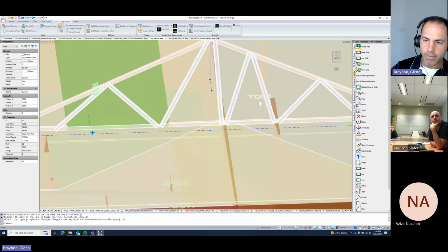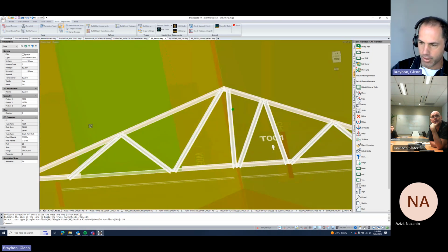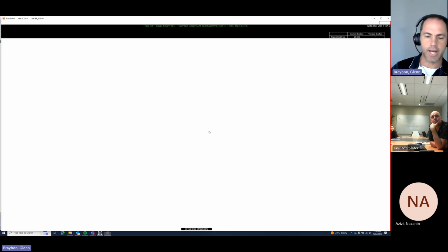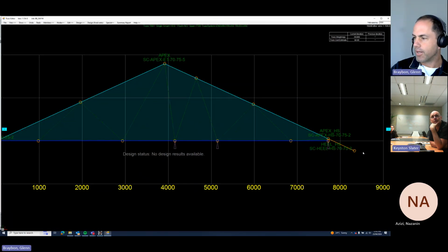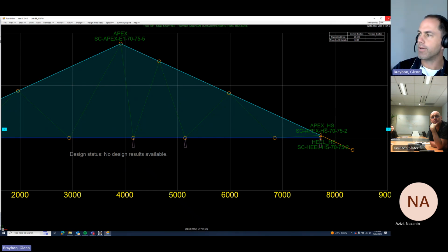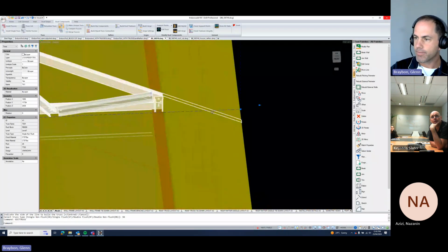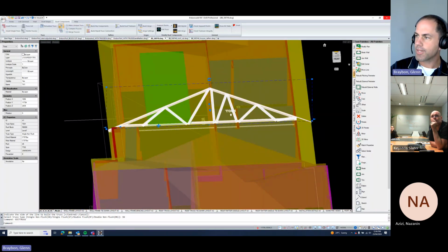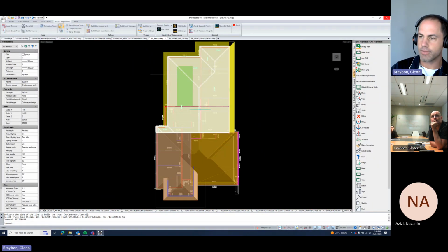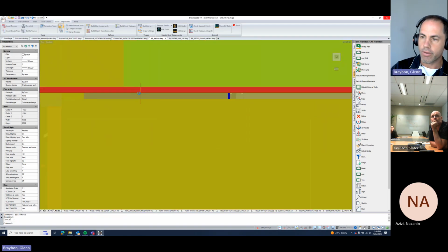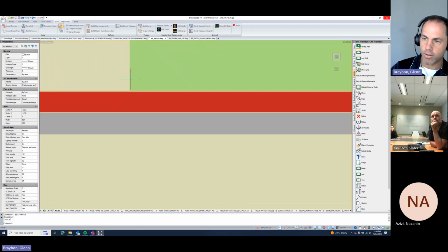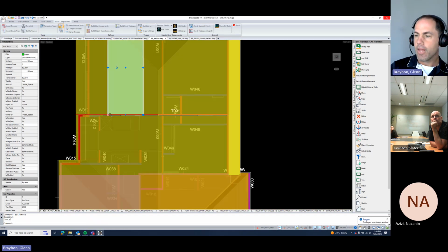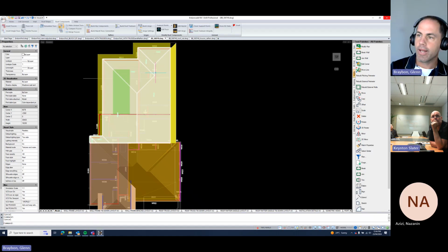I think it will. I'm more worried about that void block not picking that up. Oh, because the front side of the truss must just miss it. So if we go to edit, I think the void block is just, yeah, it's there. It's just not seen because the void block with the eave block was a bit darker. I thought the same thing when I looked at it. So I think that's cool. Yeah, looks all right. Works great. The center of that truss must just miss that void block. So I'm happy with that.